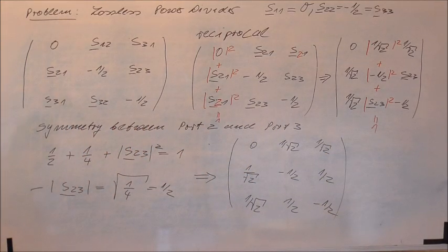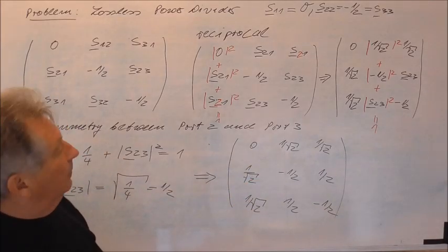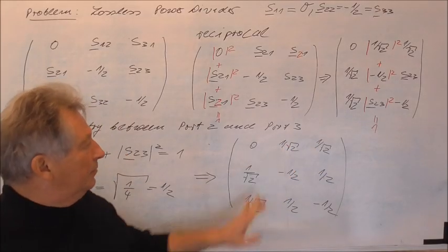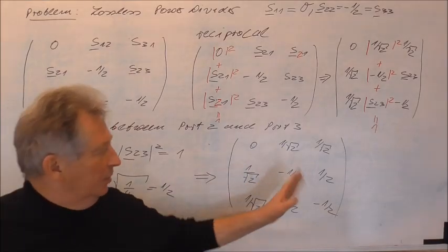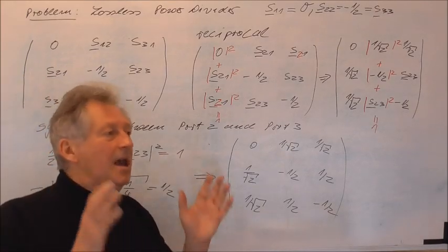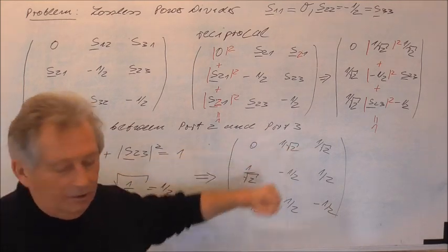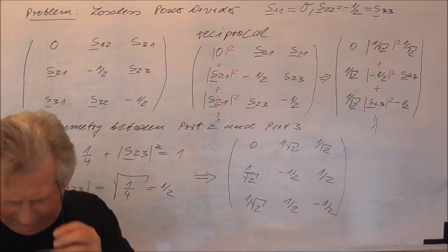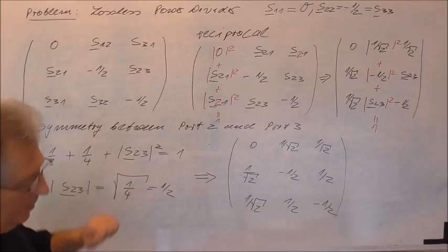And of course you again can prove this by applying the phase conditions. If you would apply the phase condition to this 3 by 3 matrix, then you would see the phase condition is fulfilled, and we can say, due to the fact that we neglect the length of the transmission line, there will be no additional phase shift in this power divider. So did this become clear, or are there questions here?